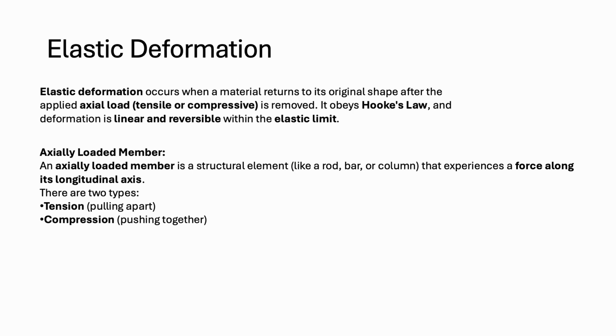So when we have axial load, we are talking firstly about elastic deformation, and this phenomenon occurs when a material returns to its original shape after the applied axial load, tensile or compressive, is removed. It obeys Hooke's law, and deformation is linear and reversible within the elastic limit. When I was talking about the stress-strain diagram, I said that the straight line is our elastic region, and that is the only region where Hooke's law is applicable, which means that stress is equal to modulus of elasticity times strain.